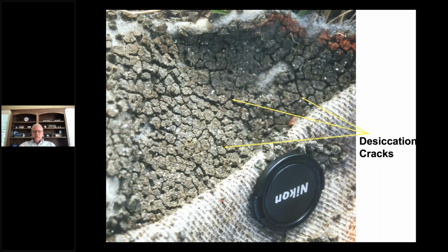Well, we dug into the system and looked at the GCL, and wow, what's going on? This is not an image like that nice swollen GCL I showed earlier. This is the bentonite in the GCL where it's been pulled apart. We see dry bentonite, we see cracks, we see some vegetation in the background. Clearly a dried, cracked system.